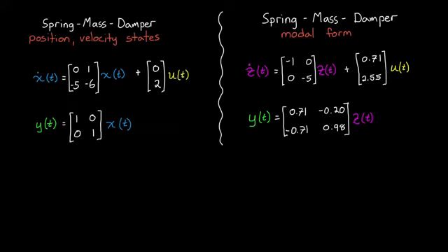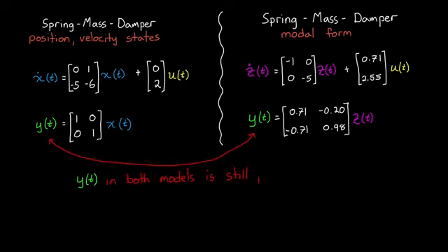There's nothing really special about position and velocity for state variables, other than they are quantities that make intuitive sense to us. However, since the states are no longer defined as position and velocity, the C matrix needs to change if we want to keep the outputs position and velocity. In this way, we can see the benefit of the output equation. We're not forced to output the states exactly as we define them, but rather have the ability to linearly combine them into variables that we're interested in.